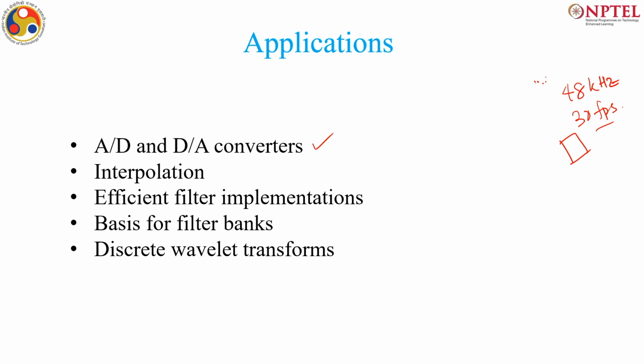When you are listening to it together, the systems or the hardware doing these operations are operating at different sampling rates. So, this is a typical example of a multirate signal processing system. Sometimes in audio processing, like mixing, you all listen to a lot of songs. In these songs, the vocals might be recorded at different sampling rates because the voice has a different bandwidth, whereas the instrumentals can be recorded at different rates because they have higher frequency content. Finally, they are combined. That is also a case of multirate signal processing.